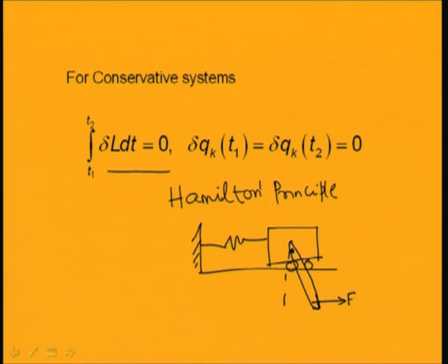In this case you can see that this reduces to a 2 degree of freedom system, because this mass will have a motion x, and in addition to that this rod will also oscillate during this motion. So you can express the motion of the total system by writing the displacement x of this mass m and the displacement of this rod.